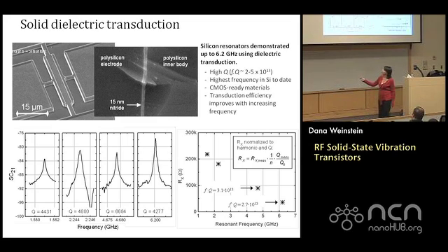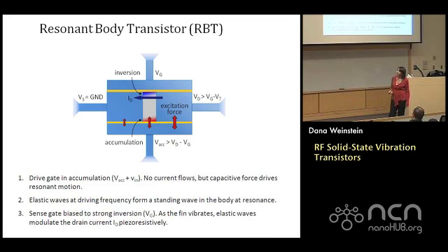And what we did was we took this bar resonator and we stuck a transistor inside of it. So what you see here is a diagram of that same bar resonator, still a silicon resonator, top view. Now it's expanding and contracting in this direction. So you have elastic waves going up and down here. And here are my two nitride films, which are sandwiched inside. And all this dark blue that you see here is highly doped, let's call it N+. And I'm going to leave this middle part undoped so that I can form a transistor.